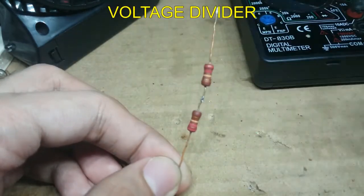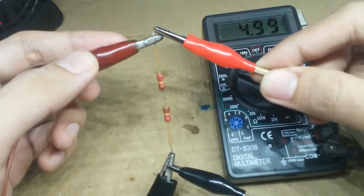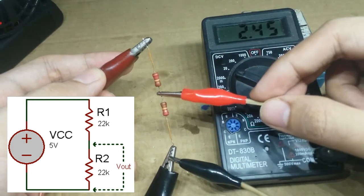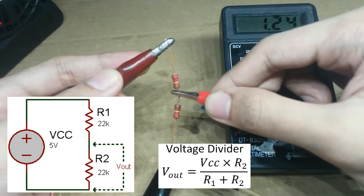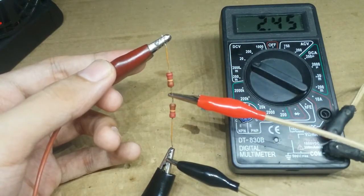Resistors are also useful in dividing voltages. For example, you have two resistors connected like this to a 5V source. The voltage in the middle will be divided. You can use this formula if you want to calculate the voltage. You will be amazed in the future how useful a voltage divider is. You can find voltage dividers in a lot of circuit designs.